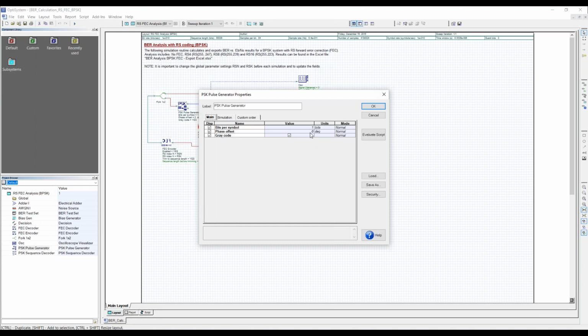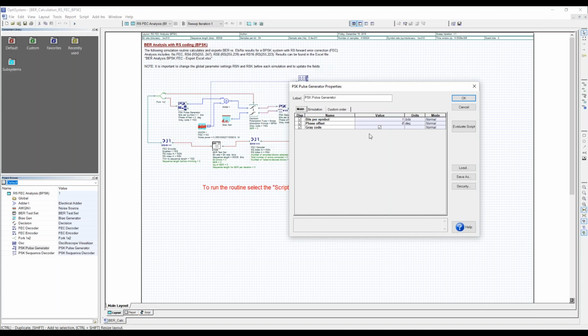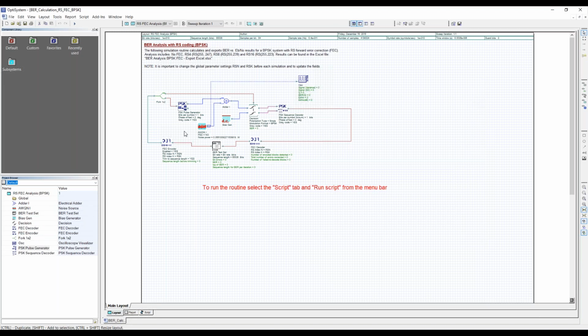Now this is the phase offset. In our situation, as we mentioned earlier, we have 2 phases, 0 and pi. If you wanted to make an offset here, let's say 40 degrees or whatever, this is used in QPSK applications and other higher-order PSK modulation. Then you can choose an offset by a certain number of degrees and run it.